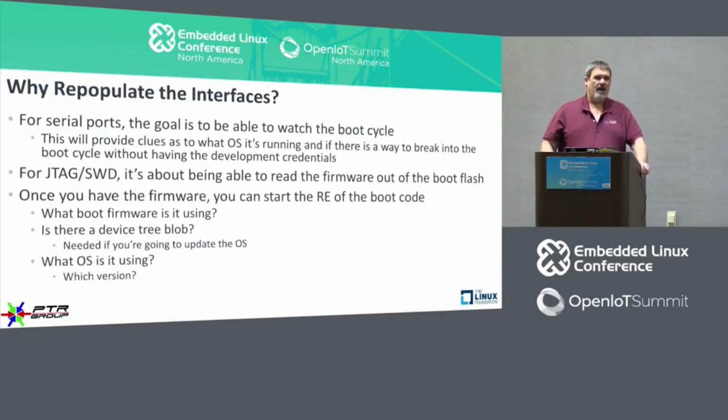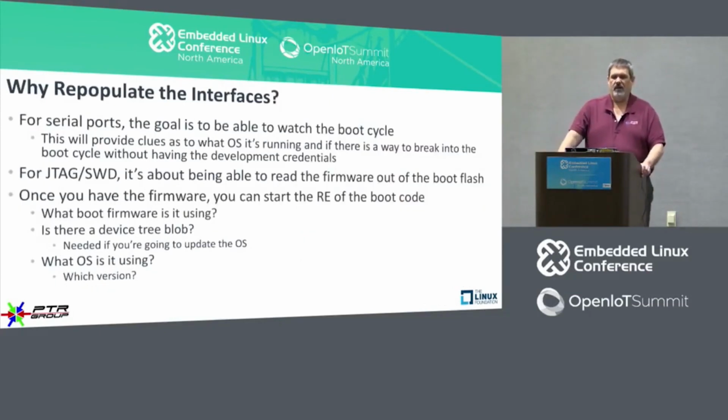All right, so now why bother repopulating the interfaces? Well, of course, for serial ports, the goal is to be able to watch the boot cycle. We want to know what this thing does during the boot cycle. We want to know if it's using U-Boot. We want to know if it's using some custom home-rolled bootloader. Of course, for JTAG and serial wire debug, the goal here is to be able to read the firmware out of the boot flash. We want to be able to grab all of the firmware because that's going to have some interesting binary blobs in it that we probably want to take a look at. And we'll show you an example of what that looks like here in a moment.